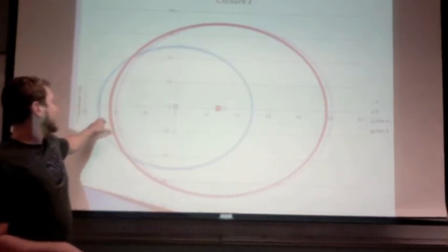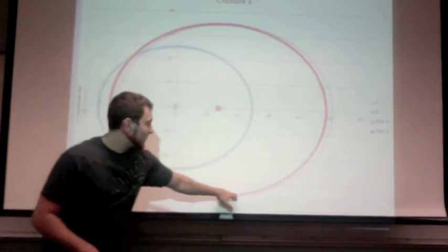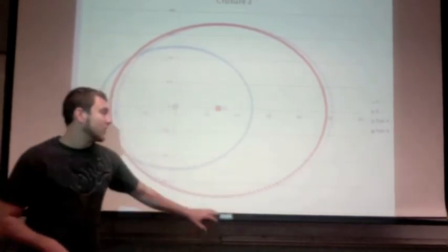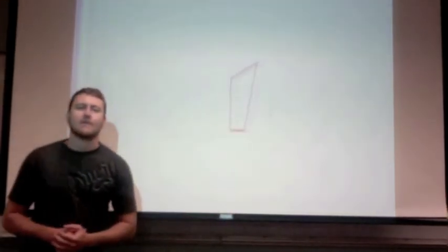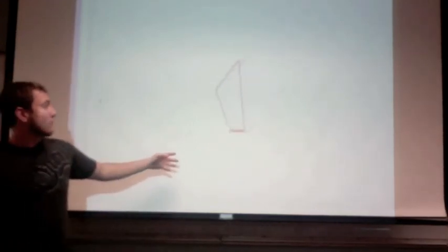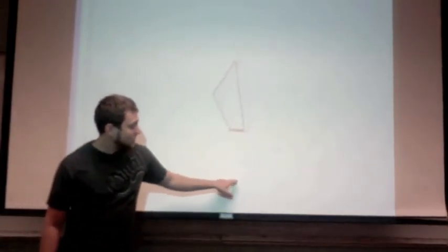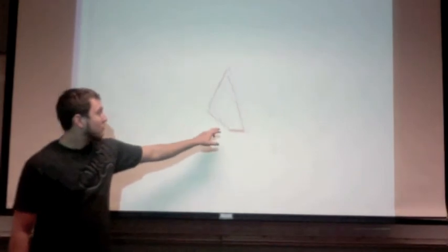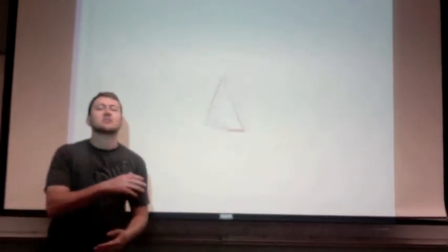And this is uniform because that's the input. You'll notice it speeds up here. There's more distance between each point on the bottom. We'll discuss that on the next slide. This is our animation of our 4-bar linkage. You'll notice that the link tumbles, especially in this quadrant right here, and that's why that joint speeds up and there's more distance between each measurement.